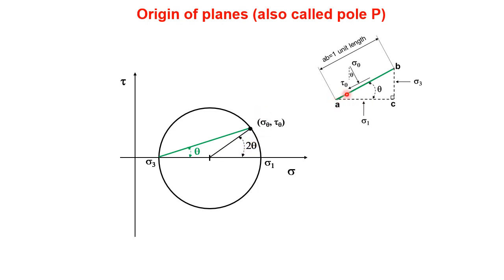So, this is the shear plane that you've just seen, and this is a Mohr circle with the principal stresses. And if I want to know what the stresses are on that plane, what I've got to do is draw a line on my Mohr circle that's parallel to that plane. That's a line at angle theta. Not quite drawn very well here, but that's the angle theta. And we're drawing a line from what we will discover to be the pole, and where it touches the Mohr circle, those will be the stresses on our plane, sigma theta and tau theta.